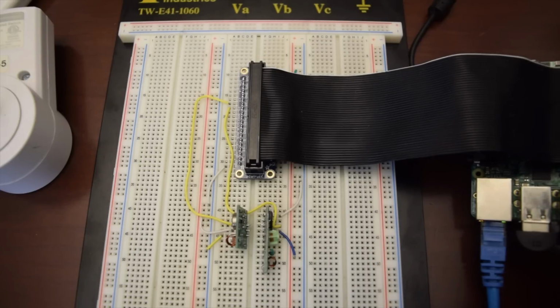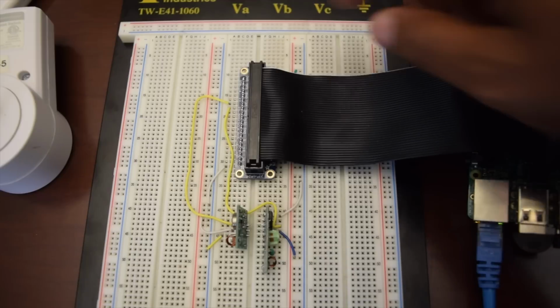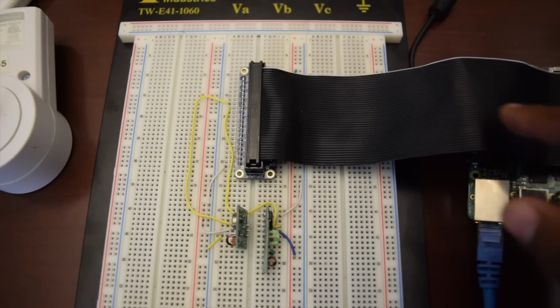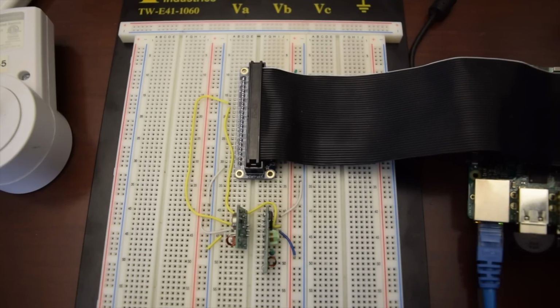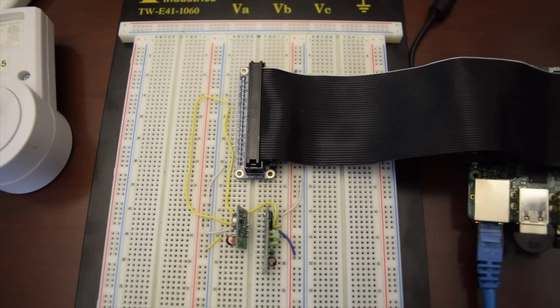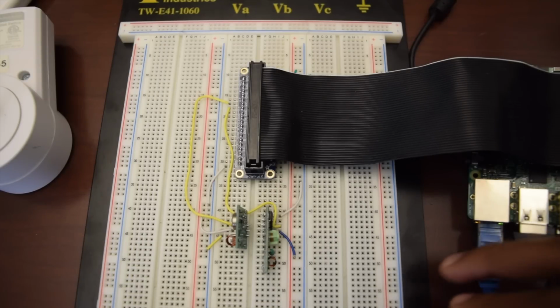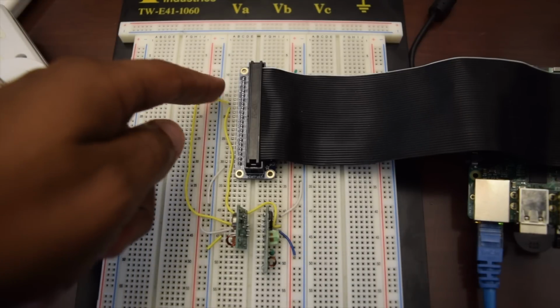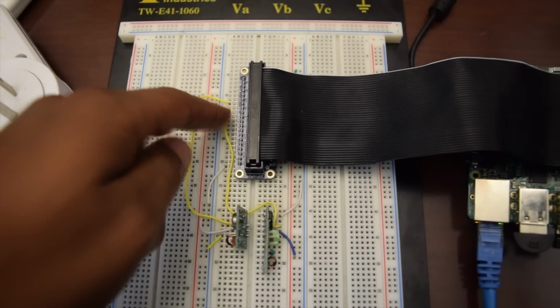To connect the Raspberry Pi's GPIO pins to the breadboard, I've set up this GPIO breakout board and GPIO ribbon. If you're setting this up at home, be sure that the ribbon's white line is on the side furthest from the USB and Ethernet ports. We also have our transmitter and our receiver pair. The transmitter has 3 pins and the receiver has 4, one of which is not used. Both require 3 connections to the breakout board. One is for power, the other is for ground, and the third is a data pin, which is connected to GPIO pin number 17 for the transmitter and number 27 for the receiver.